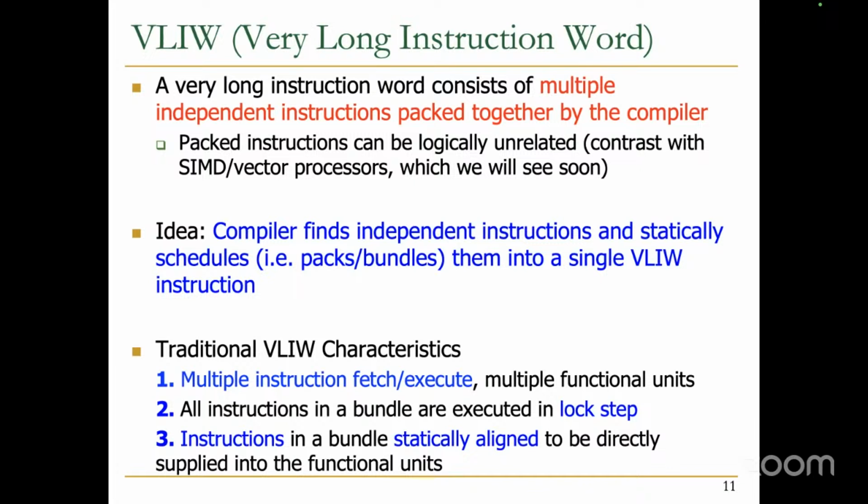We're going to see that this is going to be very difficult with memory instructions. When you do a load, for example, if you have one load in the bundle, that may need to wait because it may take a long time, right? So when that needs to wait, all of the instructions need to wait. So you stall the entire pipeline. And this is going to be one of the big downsides of this paradigm.